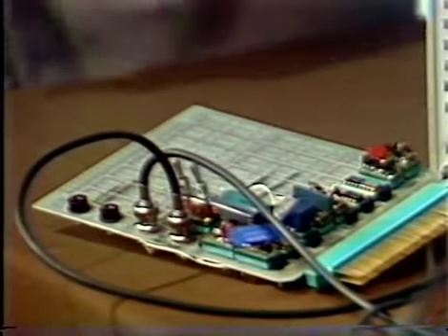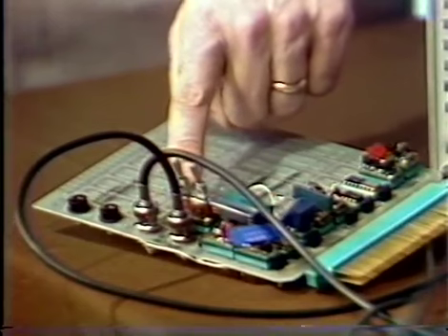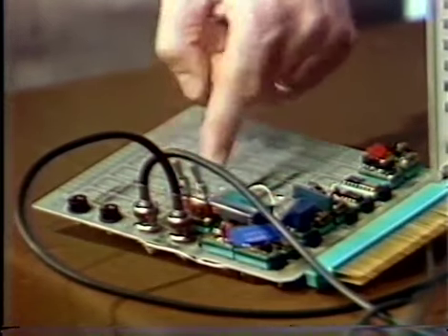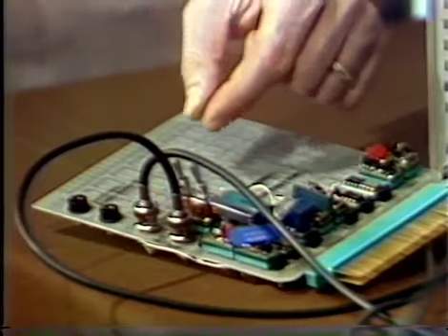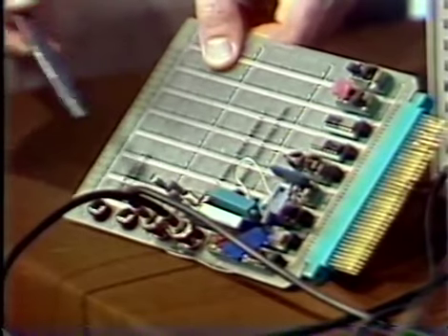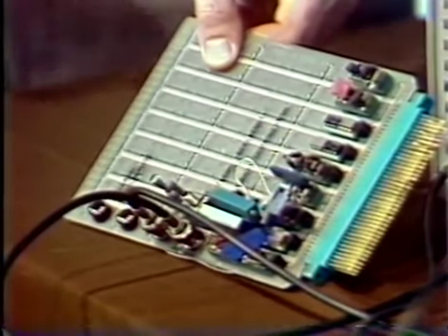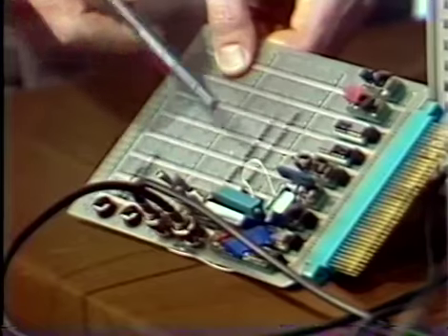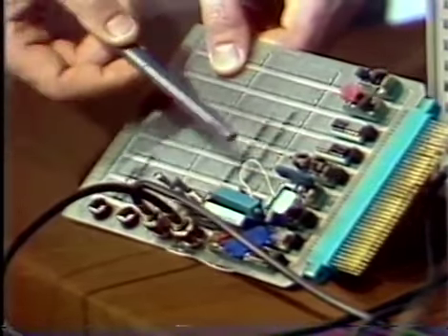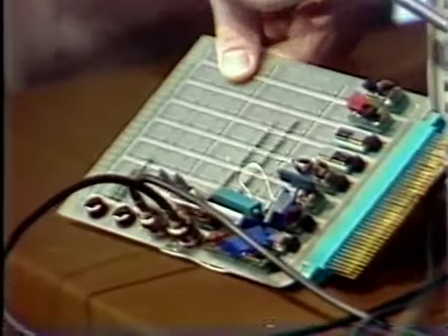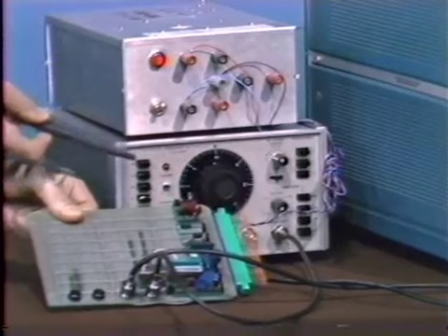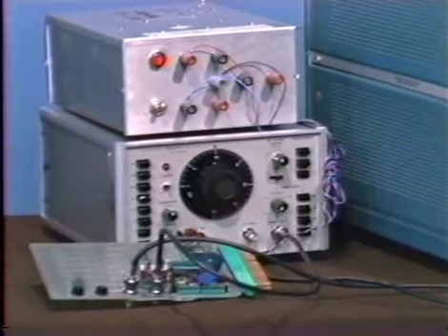There's a couple of switches, one which commands internally a fixed amplitude for the oscillation. The other position of that switch allows us to externally command the amplitude, so we can, for example, look at the step response when we command a change in amplitude. There's another switch that allows us to use external compensation. I won't do that in this case. And we have, again, the power supply test generator that allows us to command changes in amplitude, and we observe everything on the oscilloscope.